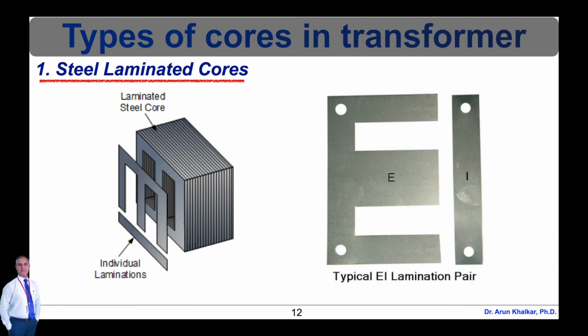The cut core or C-core type is made by winding a steel strip around a rectangular form and then bonding the layers together. It is then cut into two, forming two C shapes, and the core is assembled by binding the two C halves together with a steel strap. They have the advantage that the flux is always oriented parallel to the metal grains, reducing reluctance.